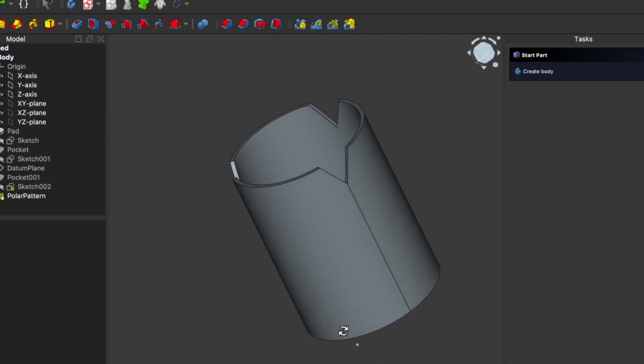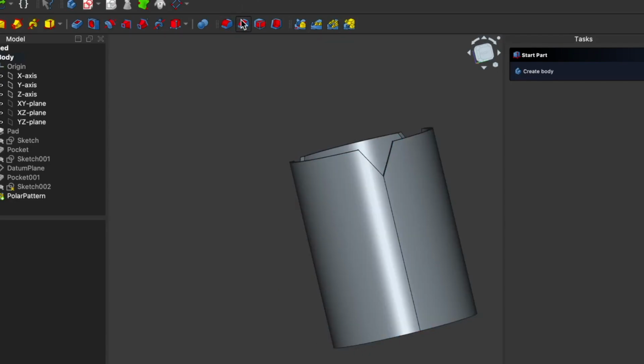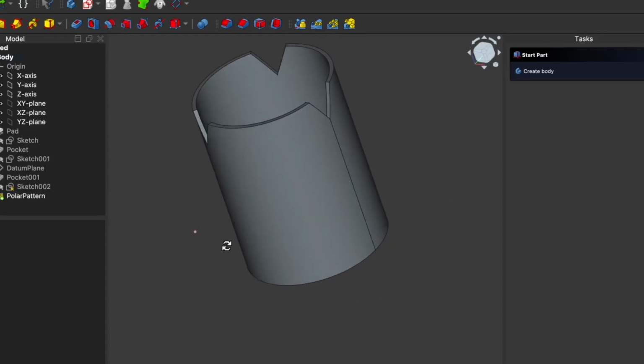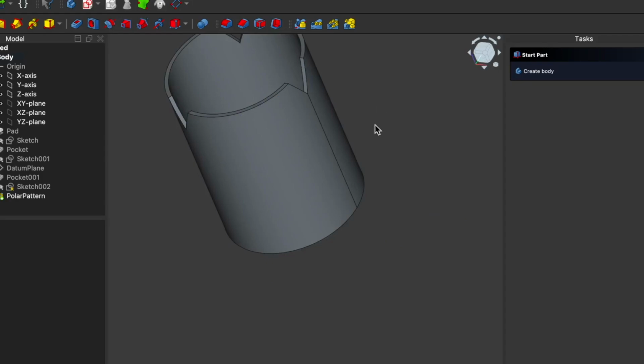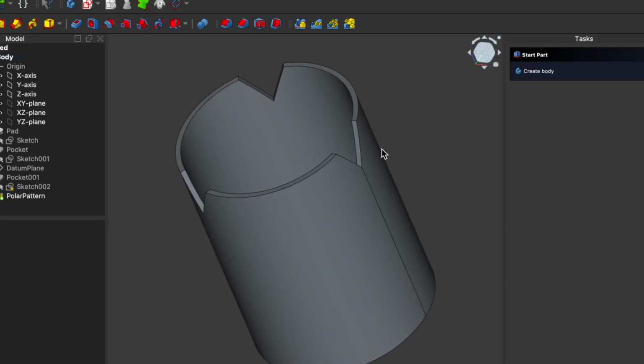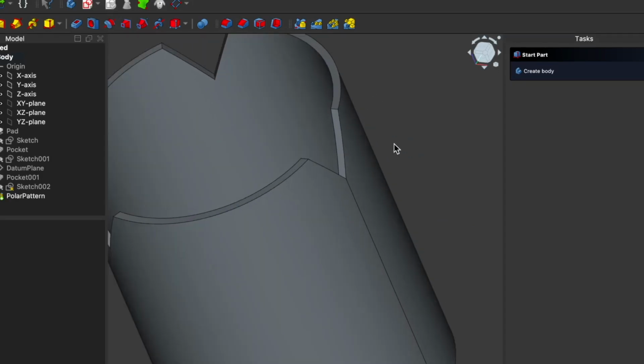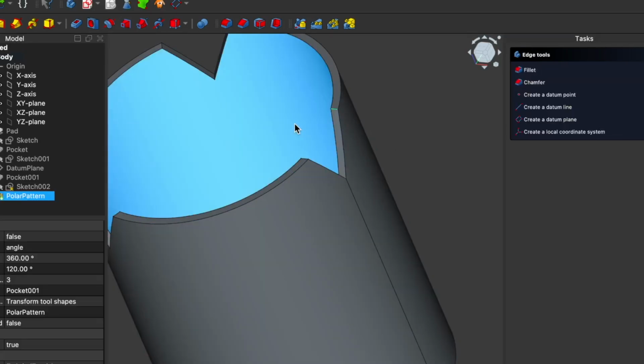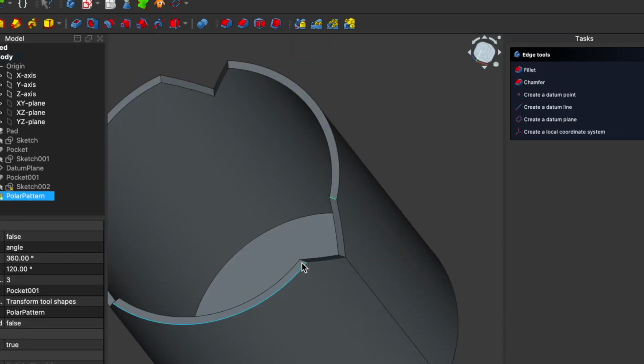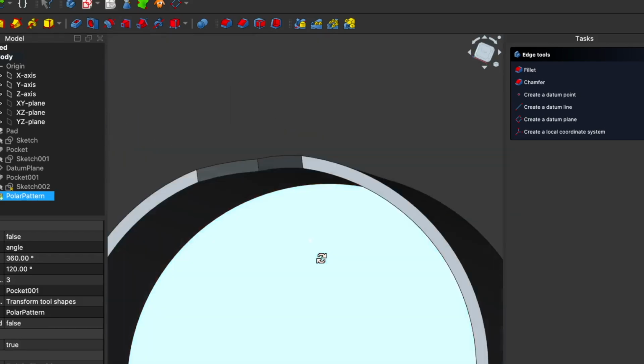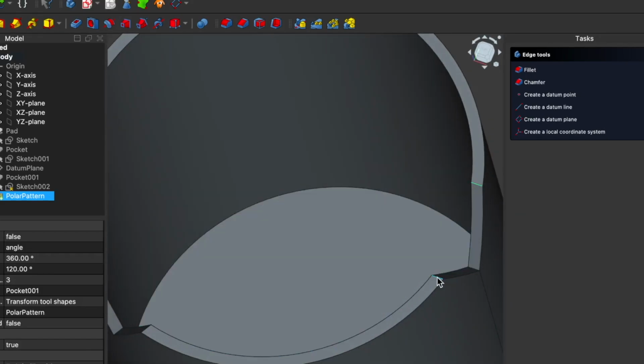And now I need to add some chamfer, like what I call chamfer, no chamfer. Let's go with fillet, right? Fillet should be pretty nice. So what we do, let me center again. Like that's FV to center, and then we want to select this edge. The other one, select the other one too. So you got to zoom in, use your mouse scroll wheel, right?